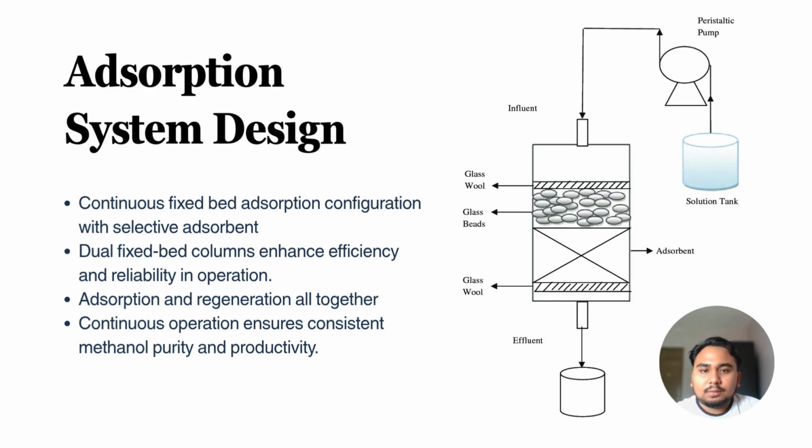The adsorbent material will first capture the water and impurities when the liquid flows through it, and this process operates under liquid phase at moderate temperature and pressure, which provides stable adsorption performance together with reduced methanol loss.